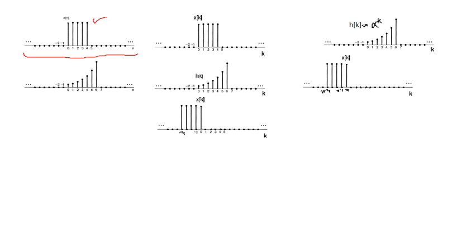The first step is to plot both the signals. So this is x of n and this is h of n. Because it is given that alpha is greater than 1, it will be an exponentially growing signal, as plotted here, right? The second step is to change the variable from n to k. So now you have x of k, and here the independent variable is k.